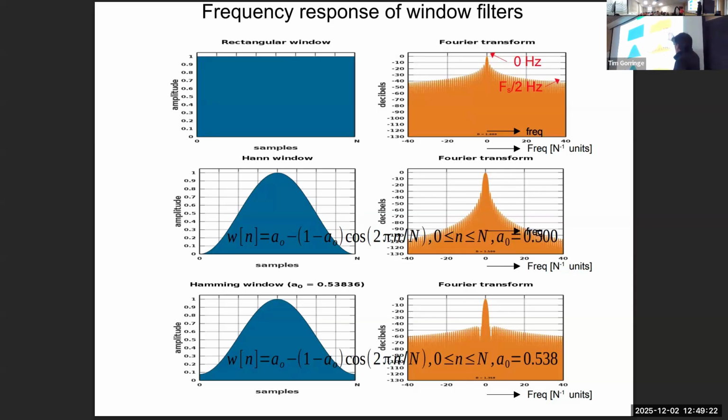That's what's plotted on the right-hand side: the three corresponding frequency responses based on these different rolling averages, the ordinary unweighted, the Hann and the Hamming rolling averages. This particular window width of n samples yields these frequency responses over here on the right-hand side.